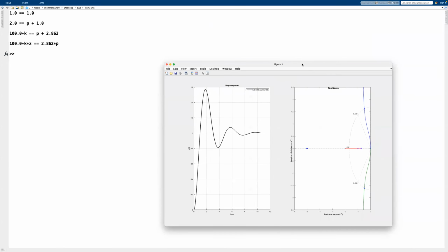Now, in terms of the root locus, you can see it's quite different because our original system had only 3 poles. One of them was at the origin, one of them was at -2, this one here, and one of them was at -5. Since we can add 2 zeros and 1 pole at the origin with a PID controller, what we did is we added just one of the poles at -5 directly to get rid of this pole here.